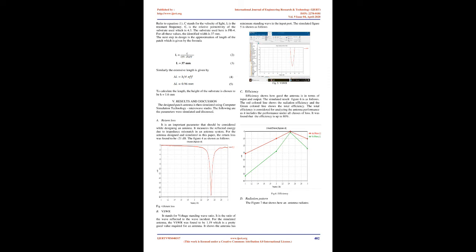This is the material which will naturally have some permittivity. Depending upon the application for which the antenna is being designed, the choice of substrate material may vary. Overhead the substrate, there is placed the important element called the patch. It is the radiating material in the entire constituent. Another important constituent is the feed. It serves as the input connecting line to the patch. In the following section, let us look in detail at the feeds used in a patch antenna.